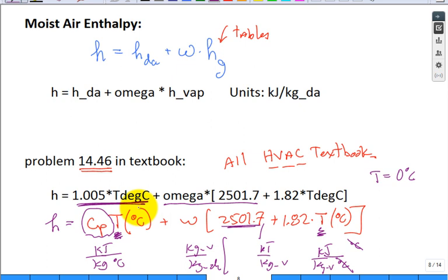And you go to the table in the appendix, the air table. Do not mix the air table with this equation, because when you compare that number with the psychrometric chart, which we're going to get to and you need to use for homework, you'll be off by large numbers. You'll wonder why it's so crazily different. Well, this equation, especially this rendition of it, calibrates it such that at temperature 0, the enthalpy of dry air is 0.